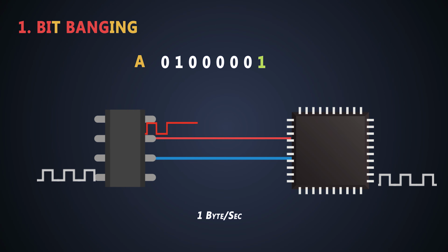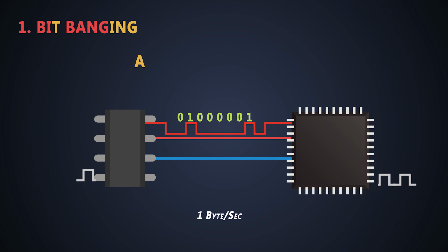The next bit is 0, so the pin goes to logic level low and it stays there for 1 second by providing a delay. And further it will stay low for the next consecutive 4 cycles to denote 4 zeros to the next device by providing delay at each cycle. Then it will get to logic high, then logic low, and 8-bit data is shifted to the next device. And finally pin 2 goes to high to stop the communication. And that's how the bit banging UART communication works.